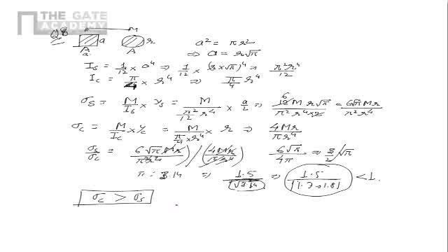We superimpose the two cross sections. So if this is the area of the square, the area of the circle will come something like this. So the top and bottom fibers of the circular cross section will be higher than the top and bottom fibers of the square cross section, which will mean that the stress there will be slightly higher.